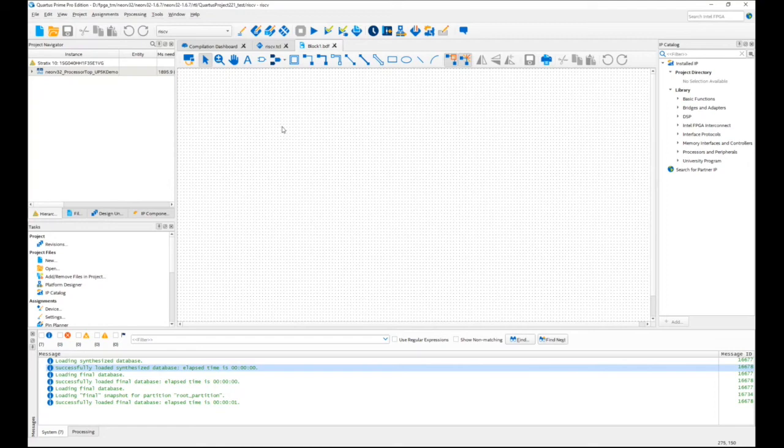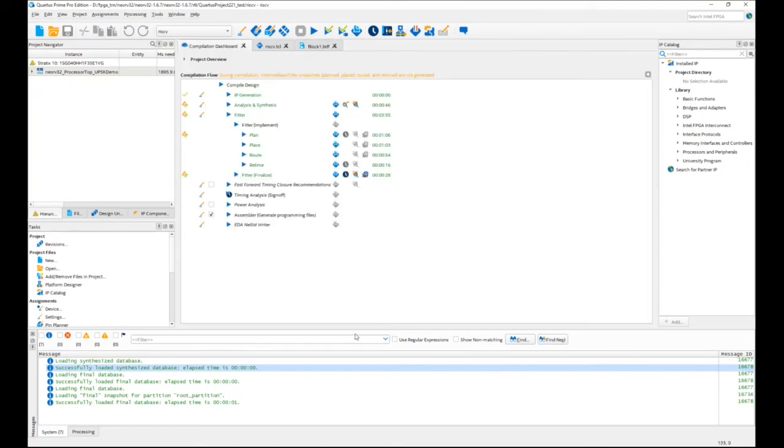Let's see, what else have we got here? Mixed language support. I'm presuming this is mixed HDL languages support in Quartus and probably in the simulation tool as well. Yes, mixed language support is definitely supported. Some people have their favorite HDL, Verilog or VHDL, and other team members want to use the other. There's no problem with mixed language support.